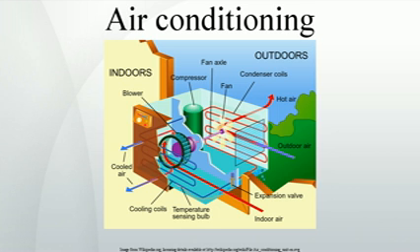This can also be rewritten as, for example, a 5,000 British thermal units per hour air conditioning unit, with a SEER of 10, would consume 5,000/10 = 500 watts of power on average. The electrical energy consumed per year can be calculated as the average power multiplied by the annual operating time. Assuming 1,000 hours of operation during a typical cooling season, that is, 8 hours per day for 125 days per year. Another method that yields the same result is to calculate the total annual cooling output.